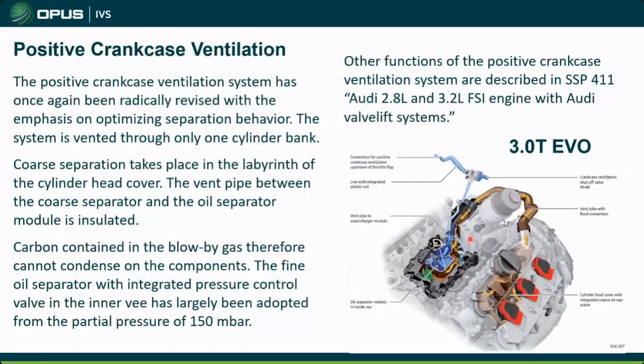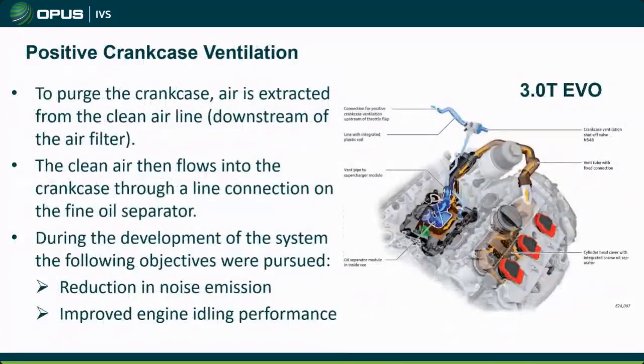And why would you want to do that? Well, there are some circumstances where that might be good. Oh, the other thing to note is that you only have one vent pipe. The bank one does not have a labyrinth in the head anymore. In the valve cover, there's no connection to it. You only have one hose, and it comes on the driver's side. So, trying to simplify the system, reduce the number of components, and I imagine try to make it operate a little bit better.